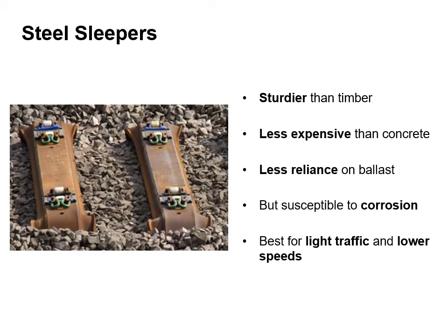Steel sleepers are generally sturdier than timber. They're less expensive than concrete. There's less reliance on the ballast, but they're susceptible to corrosion. They're best for light traffic and for lower speeds.